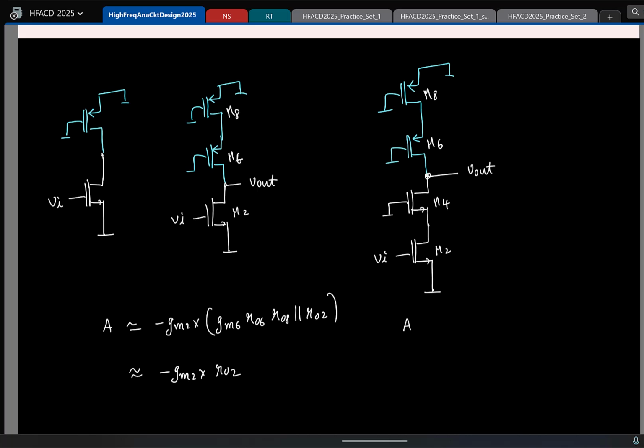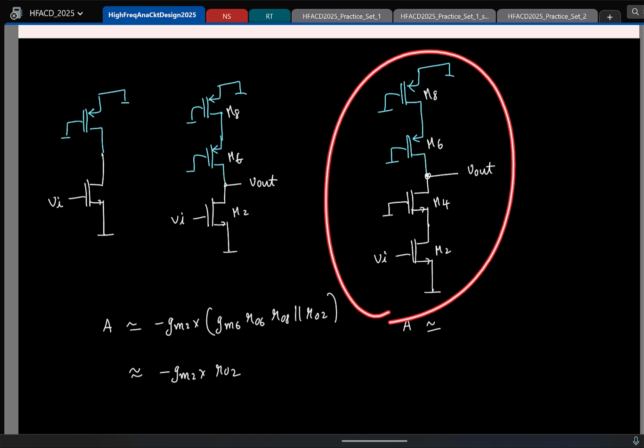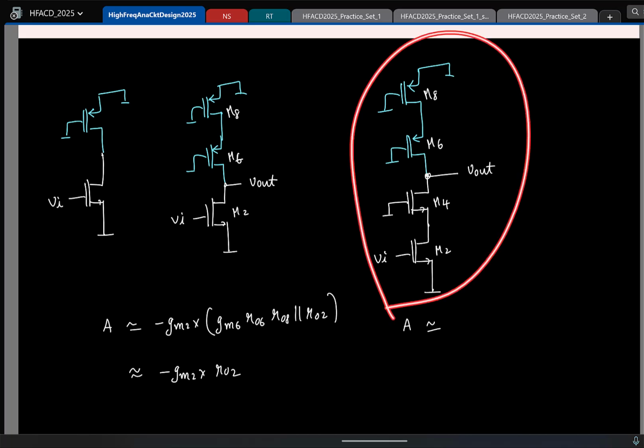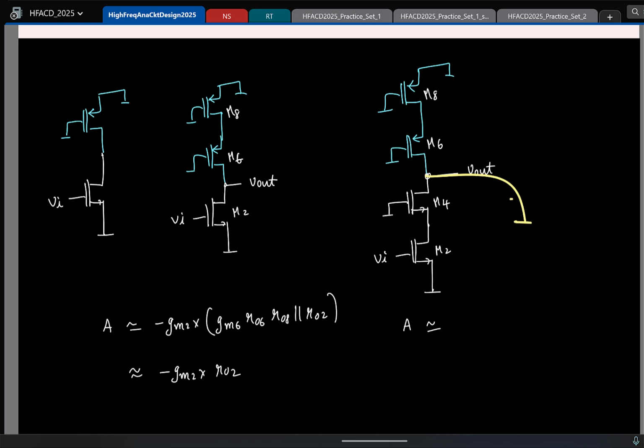So now what is the small signal gain here? What is the short circuit gm here? What is the short circuit transconductance here? That is, if I short circuit this, what is the short circuit current flowing? Can you check? Yeah, minus gm2 vA. Be careful with the signs. So the short circuit transconductance is gm2. It shouldn't be so shocking because we didn't do anything to change the transconductance. The only thing we did was to increase the output resistance.